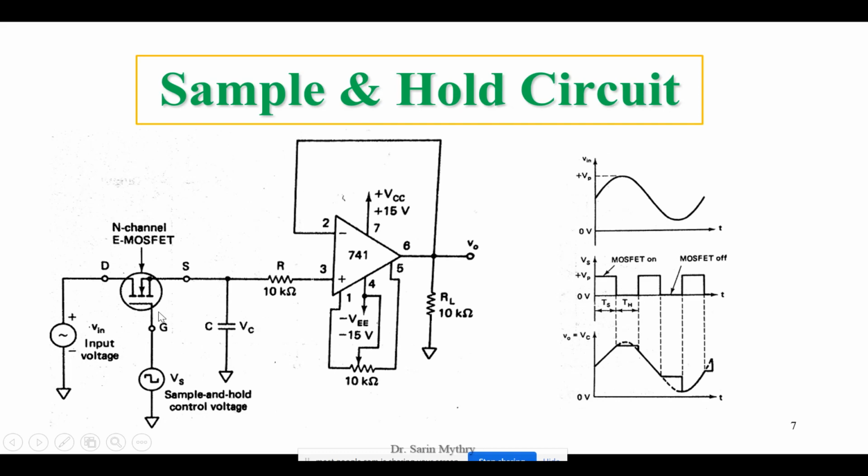See, it means that whenever we are supplying some input voltage, that input voltage is traveling through the MOSFET and is being stored in the capacitor. And whatever the input voltage is stored in the capacitor will appear at the output Vout. So whenever this MOSFET is turned on, you have some output voltage depending upon the charging of the capacitor due to the flowing of charge from the input voltage into this capacitor. So now let us go to the other part.